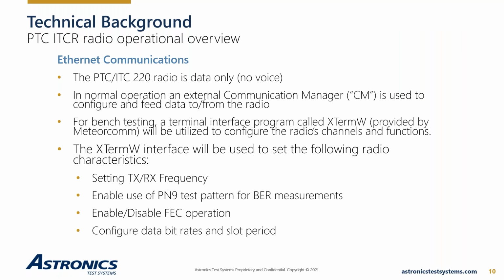For our test purposes, we're going to be doing bench tests. That means we have a single unit connected to the 8100, and to handle the control of the radio, we'll be using a piece of software referred to as XTerm-W. This is software made available by MeteorCom to whoever has this equipment. It has a little bit of built-in capability in the sense that it's aware of what it's talking to, so it's not just terminal software. It actually knows the equipment it's talking to. It knows how to set up initialization characteristics and get the unit operational.